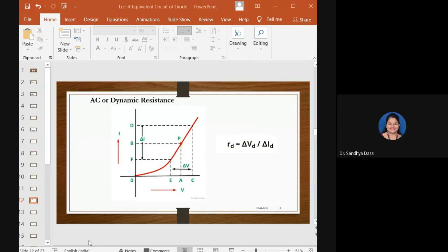Correct, correct. So how do you put it in the right form? Very good, Ashwija. Can I alter your answer, saying that the slope would be y2 minus y1 by x2 minus x1? Will that be fine? Yes, ma'am. Right. So the slope of the curve would be y2 minus y1 by x2 minus x1, right? From there, we can measure the dynamic resistance as given by the equation here, which is nothing but the change in the voltage to the change in the current.